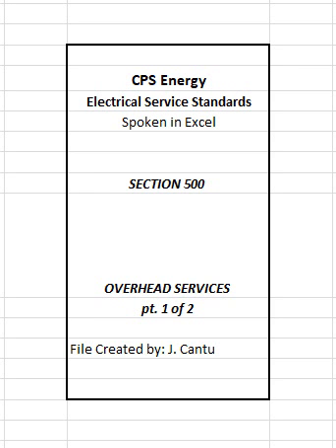503.1 Windows, doors, porches, balconies, etc. Service drop conductors and drip loops shall have a horizontal clearance of not less than 5 feet from doors, porches, balconies, ladders, stairs, fire escapes, windows that are designed to be opened or other similar locations.